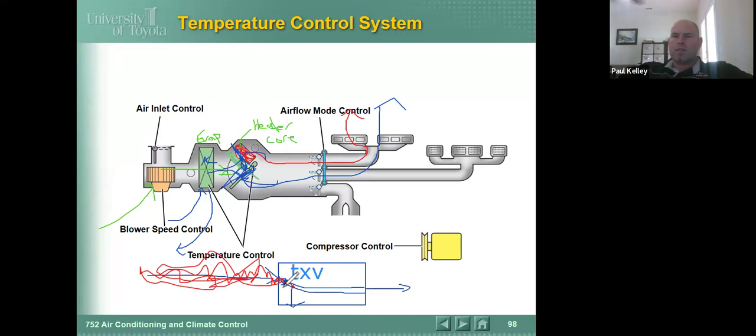So let's say the TXV fails, your high is too high, your low is too low. That's a TXV that's restricted. Should that TXV open more? Yes, but it's restricted. You'll never get a TXV that's confused. A TXV doesn't do the opposite thing. It doesn't say, "I'm supposed to open, but actually I accidentally closed." You know what I'm saying? What'll happen with a TXV is it'll be restricted, in which case your high will be too high, your low will be too low.